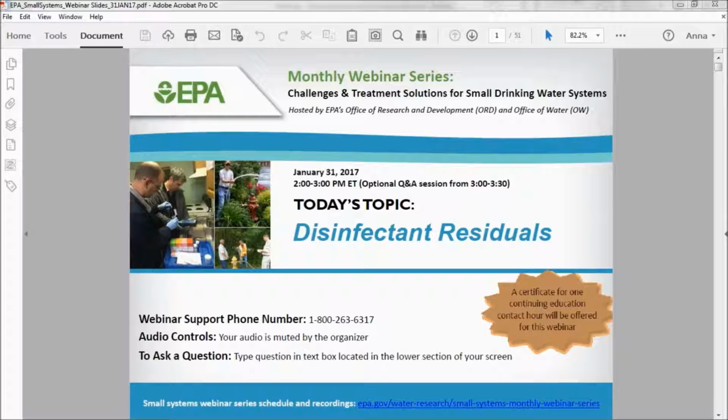Okay, and the second question was, if you are using a DPD chlorine kit to measure the free chlorine residual in a chloramine system, will you get erroneous free chlorine readings, and if so, why? Does the ammonia interfere? Well, this is maybe something Jonathan or Dave could help with as well. I don't think it's the free ammonia that necessarily interferes with the free chlorine. I think it's just interference with monochloramine or other interfering agents.